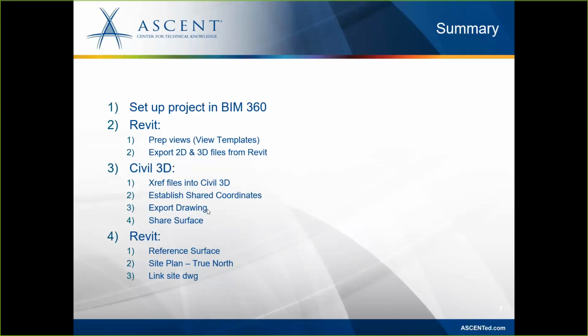Again, as a precaution, I actually extracted the contours, and I made sure that the XREFs were bound into the drawing as a block. And then I also shared my surface. And then going back to Revit, we referenced in the surface.